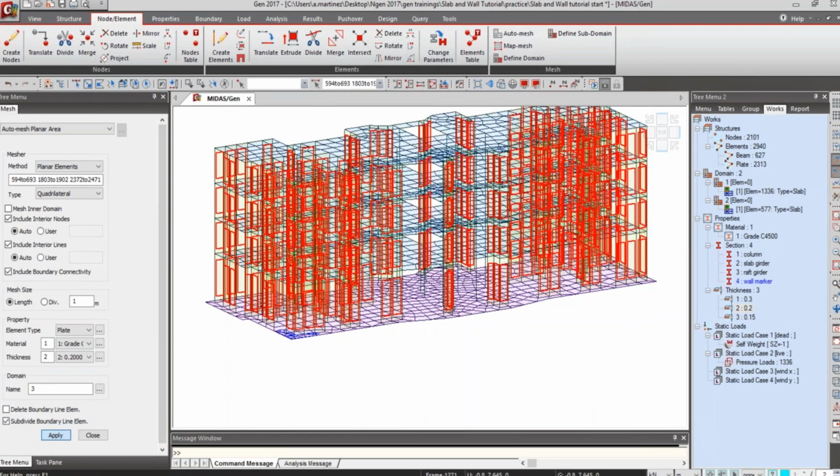The reason we waited to mesh the walls until after we made the copies of the stories is that the stories are different dimensions. The first story is longer, almost by 30%, than the other floors. But if you were just going to make copies of floors all the same height, you could mesh the wall first and then make copies.